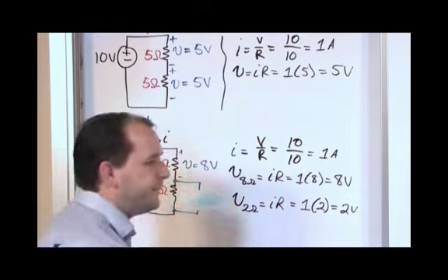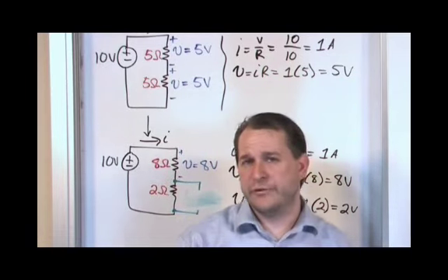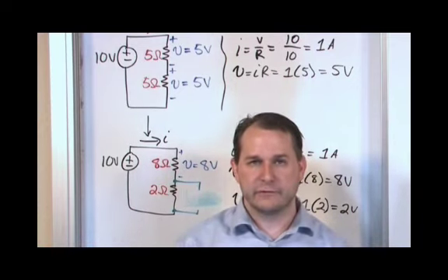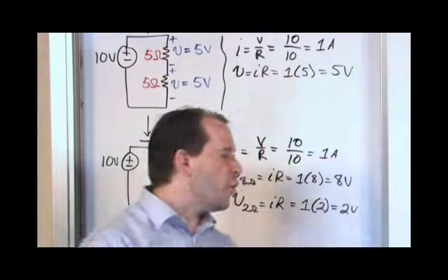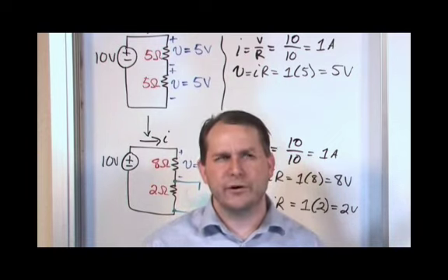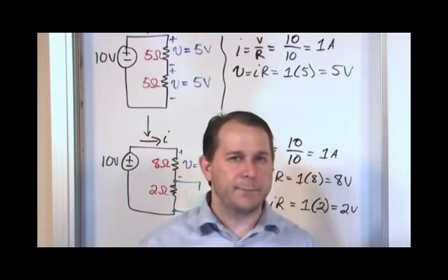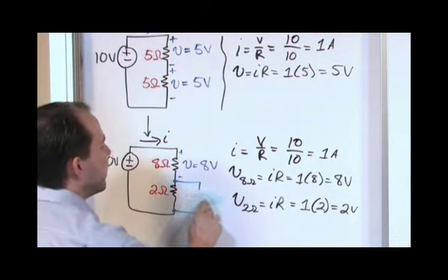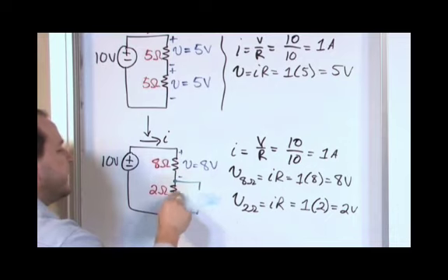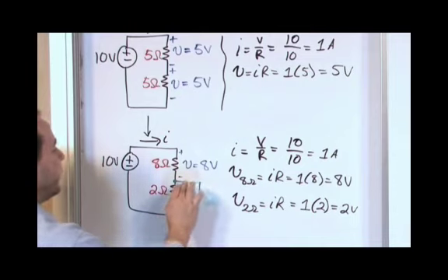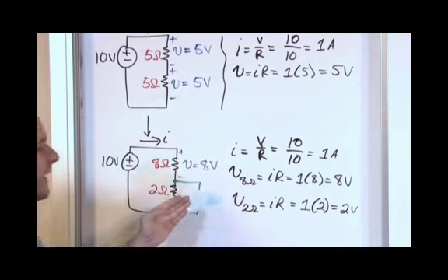Now when you think about it, as soon as I connect the load, which is some resistance, like if it's a light bulb, it's a resistor. That's what a light bulb is. So let's just pretend it's a light bulb for the sake of discussion. So I hook a light bulb up to this. At the moment I hook a load up to it, I've altered the circuit. It's no longer pure the way I originally designed it. I'm introducing another resistance here, the resistance of the load, and this resistance is in parallel with my 2 ohms. So if I put the wrong kind of resistance here, I can change the value of this whole area of the circuit, which will alter the voltage going into my load.